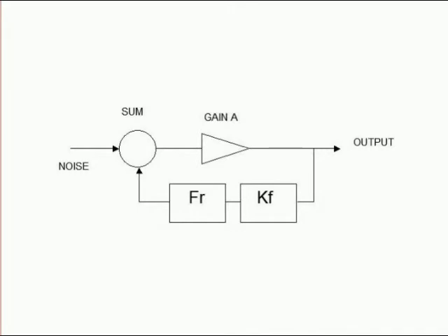Because a practical oscillator has a very vast gain due to the positive feedback, the tiniest amount of limiting has a very powerful effect on controlling the amplitude. But in this theoretical system we've got no method of doing this. So what we're intending to do is, hypothetically, imagine an AGC system which will, with a very long time constant, control the gain of this amplifier to maintain a constant output.